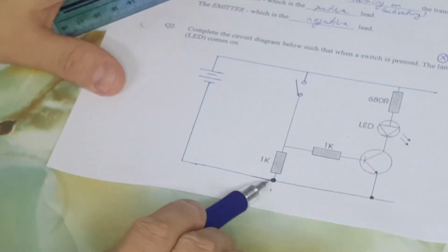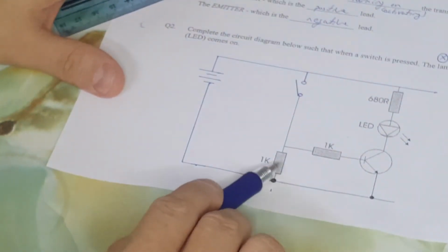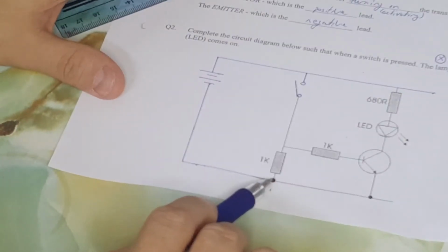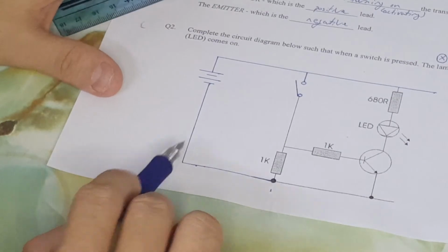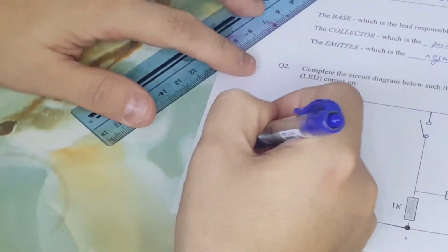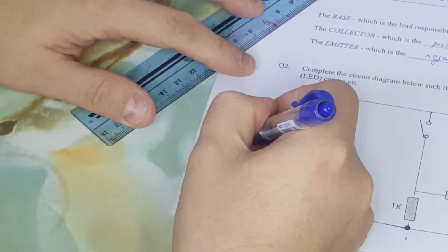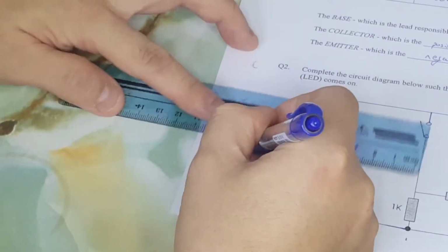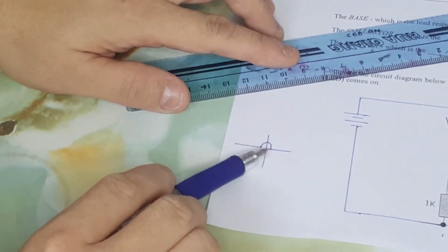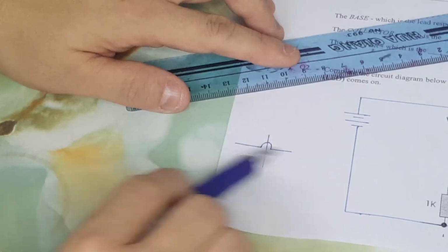If you see little dots here, what it means is that the 1 kilo ohm resistor is actually connected as well. So if you want to, for instance, show a wire running across another wire in another circuit, in order to avoid confusion, you create a bridge that jumps over. So what it means here is there's no connection between these 2 wires.